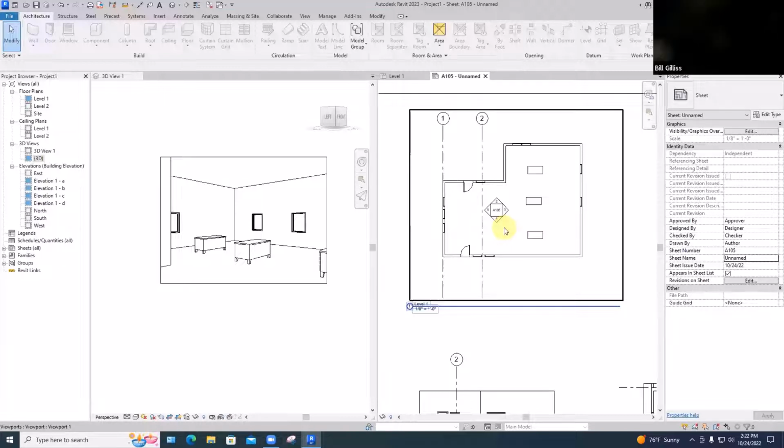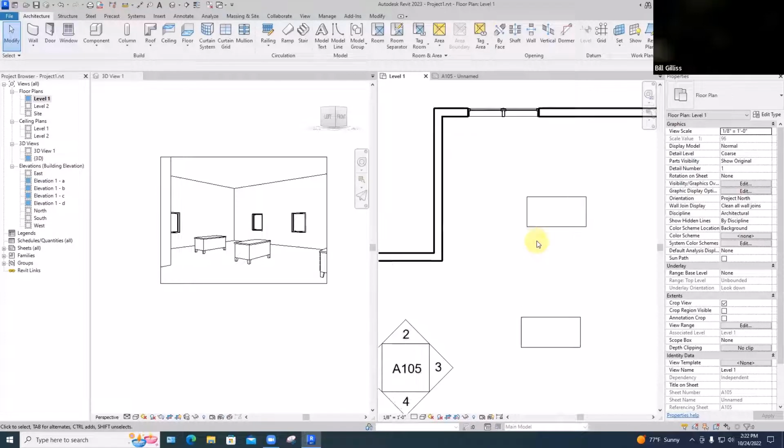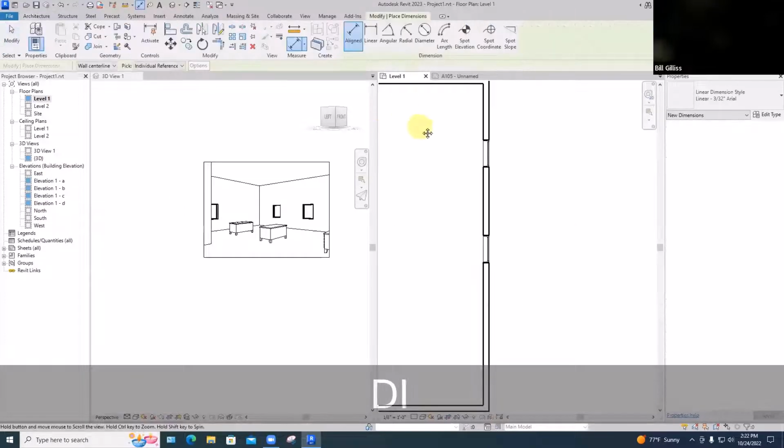There's one other really significant difference between Revit and AutoCAD. In AutoCAD, there's always the question of, do I dimension in my model and then worry about the size of the text once I get where I'm going? How does that all work? And Revit really takes care of that completely well. First of all, since there's no model space, you don't dimension in model space. Making dimensions here in a view, and let me just do that. DI for dimension.